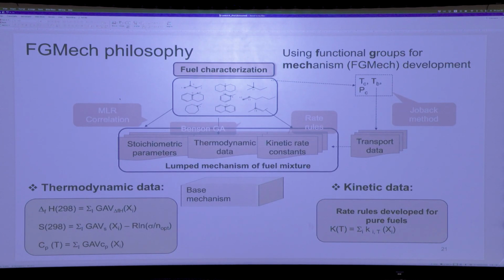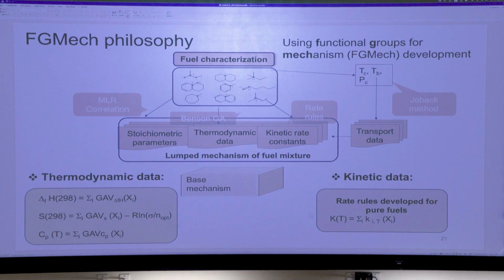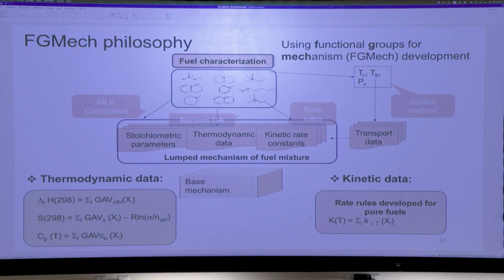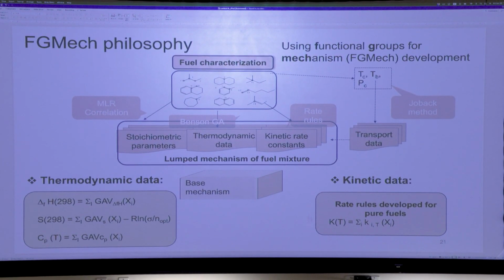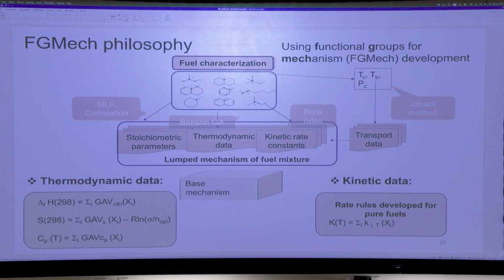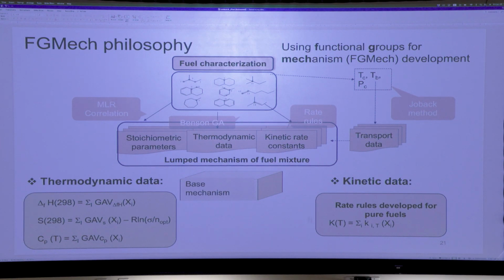And we need to figure out a way to get all of these only from the functional groups present inside of a real fuel. So, of course, we need to know what is a fuel, right? Because the fuel functional groups are necessary to build this model. This can, again, be done by NMR or by a detailed hydrocarbon analysis that's typically found in an ASTM standard methodology. From a characterization of the fuel, and of course, a non-reactive experiment, simply the fuel. You're not doing any special reactive experiments. You're just measuring the functional group distribution of the fuel.